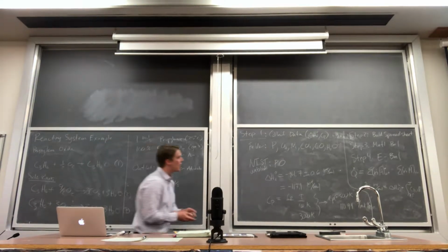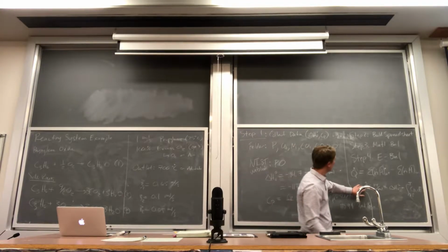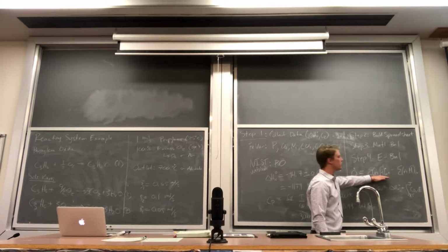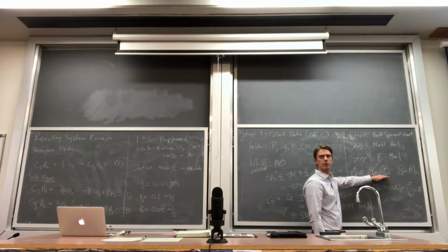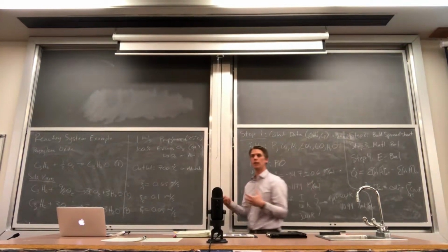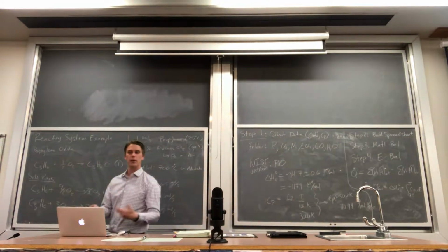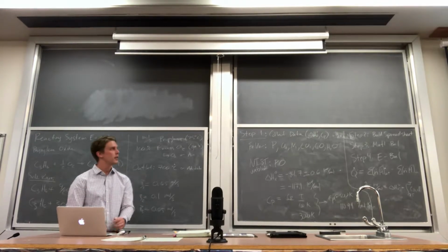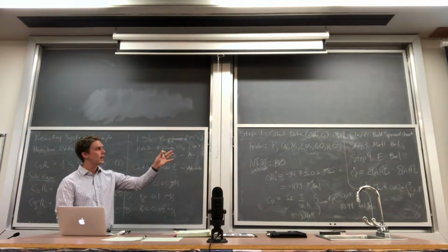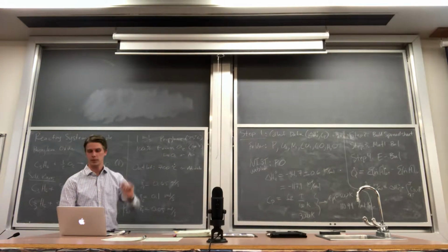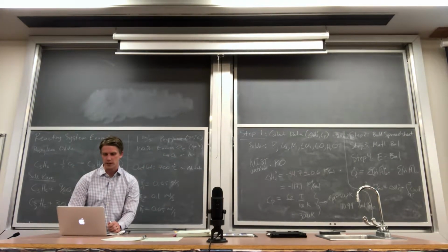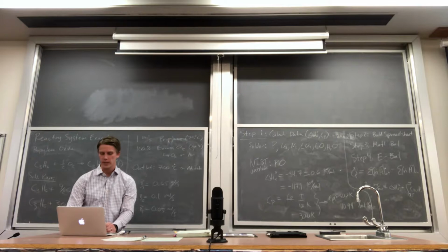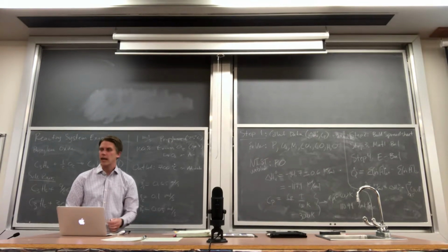Now, but this is not what I really care about. What I really care about is the summation of the flow rate times the specific enthalpy to give me units of energy. Because in my energy balance, everything has to be units of energy. So this step here, all it does is multiply the flow rate times its specific enthalpy, and then of course it's the same exact formula going all the way down, and at the end, I just add it all up.